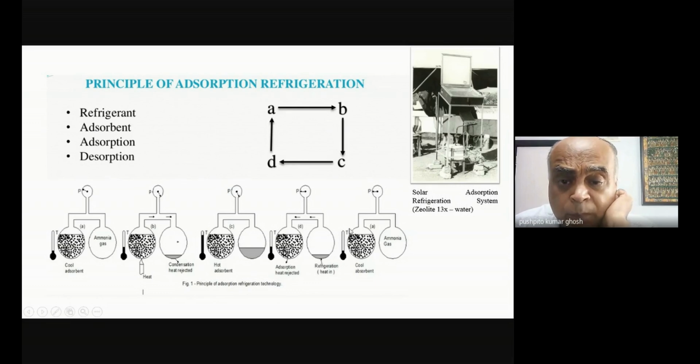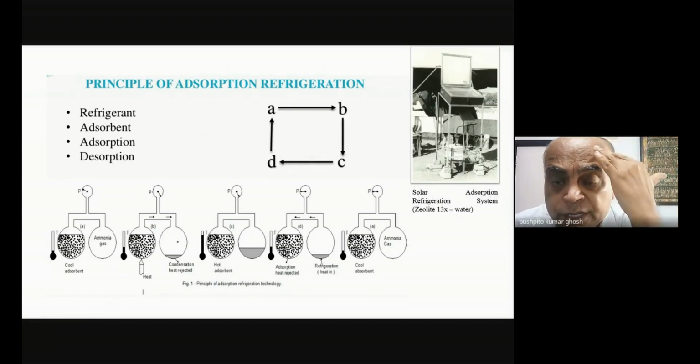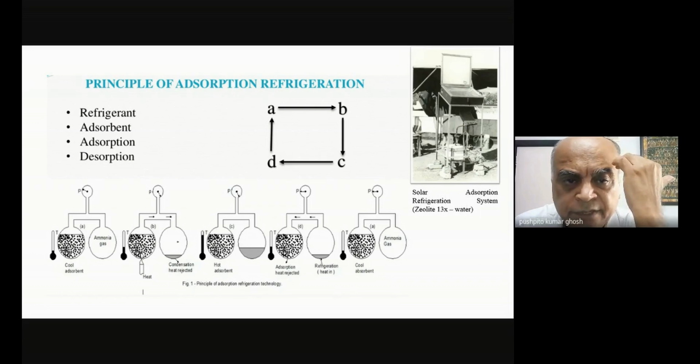And the more my temperature goes down, like let's say in the night, when it is reasonably cold, even in very hot places at night it can get quite cold, all the ammonia basically reverses and comes back here, and I just have to restart the whole cycle. And this, for example, is done in the zeolite 13x system. But effectively, that's the way in which you are doing things.